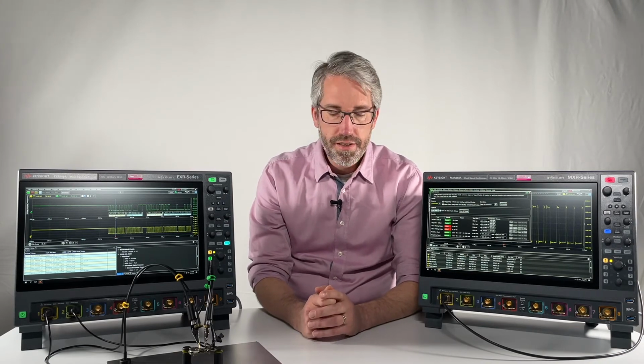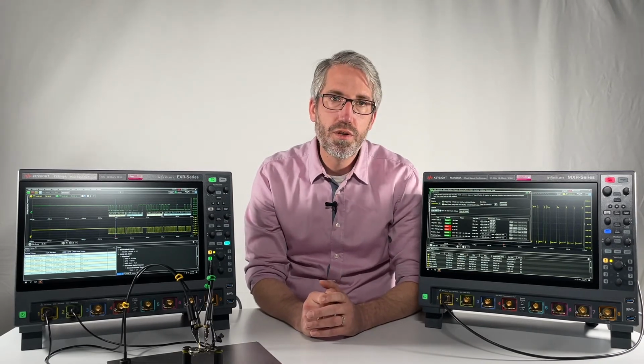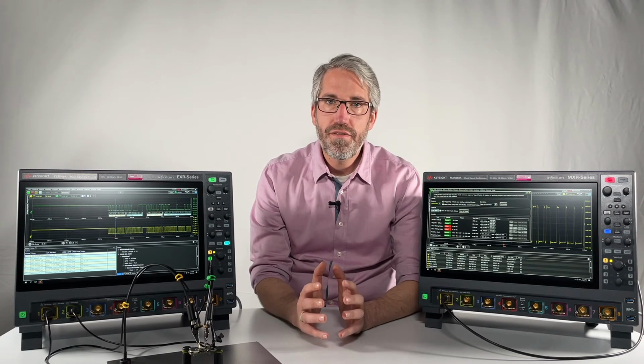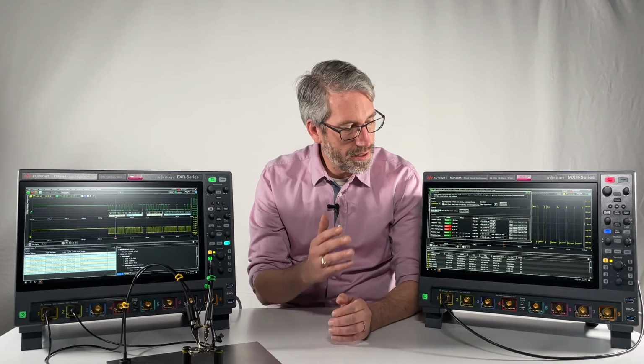Now last but not least, there's a pretty neat feature on both oscilloscopes. It's called the fault hunter. You can actually see it running here. The fault hunter analyzes the input signal with statistical means, and by doing so it is capable of detecting a single event which causes an error among billions of events. Now think about this, this is really tremendous and not seen before on any oscilloscope. And the really nice thing is you can let this feature run for up to 2 days without any human interaction. So you can let the oscilloscope search for this single error among many other correct signals without any human interaction.